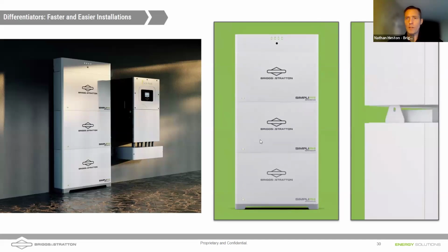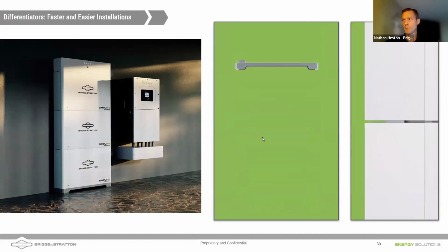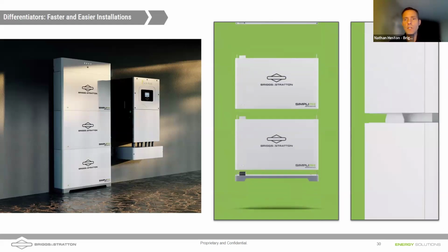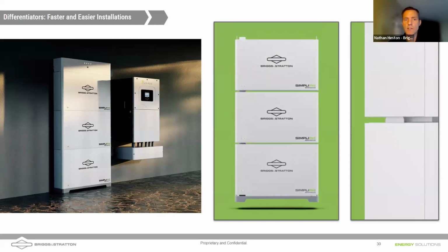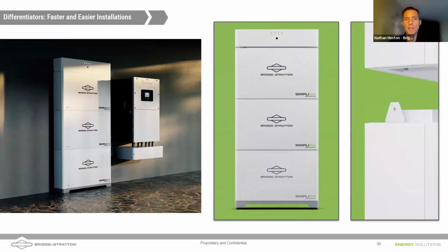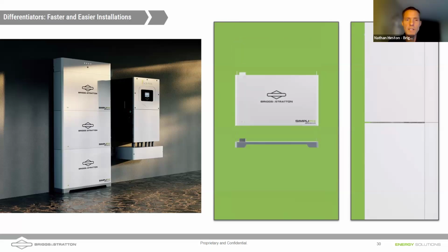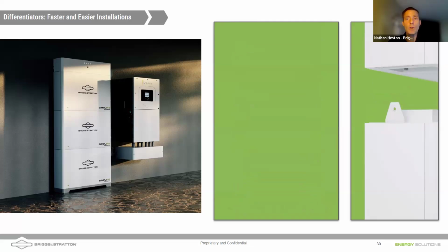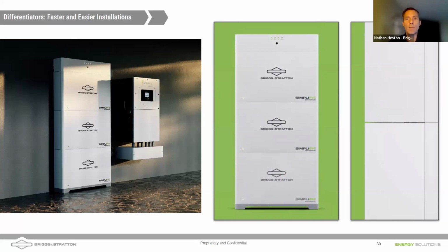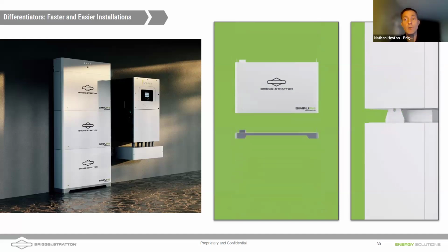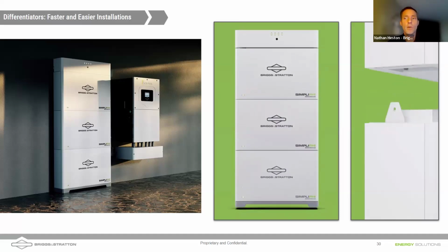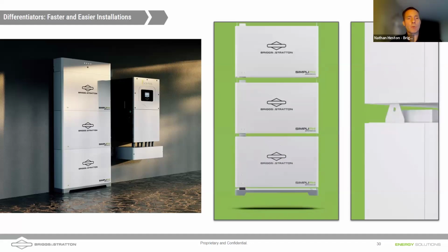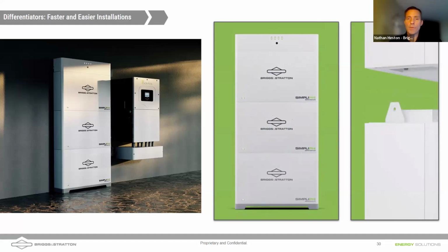I do want to share a few things in terms of the 6.6 battery, what it looks like, how the installation goes, etc. What you see on the right is that the battery is stacking. You're looking on the left at a floor mount example of the stackable 6.6. That's a 20 kilowatt hour battery pack. It will typically last a whole house somewhere around 8 to 10 hours. If it's a house like mine, which doesn't use a lot of electricity, it could last up to 24 hours. My home typically uses less than 20 kilowatt hours a day.